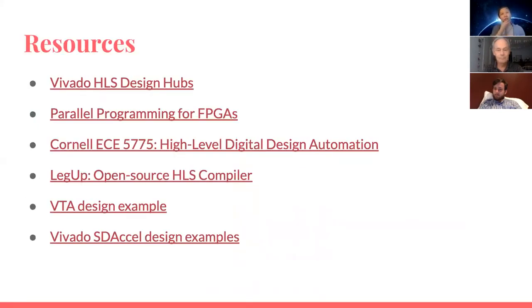There are many different resources you can look up for how to design your accelerator with high-level synthesis. I think once you get one design working, the later iterations will become easier and easier. There are also a lot of optimizations you can do with the high-level synthesis compiler. So I encourage you to look at the Vivado HLS design hub, and you can just play with high-level synthesis on your PYNQ board with IPython notebook. It should be fairly simple: you can write a C-like program, and then have hardware to accelerate those C-like programs.